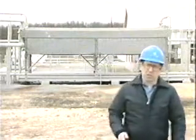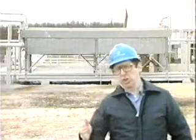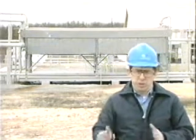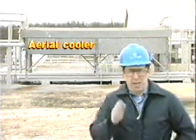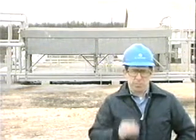As we mentioned earlier, gas temperature increases as gas is compressed. So to control gas temperature, discharged gas is passed through a cooler to remove some of the heat. Usually it's an aerial cooler with separate passages for compressed gas, water, and lubrication. Now, part of the cooler may have passages for water to cool the prime mover and compressor cylinders.